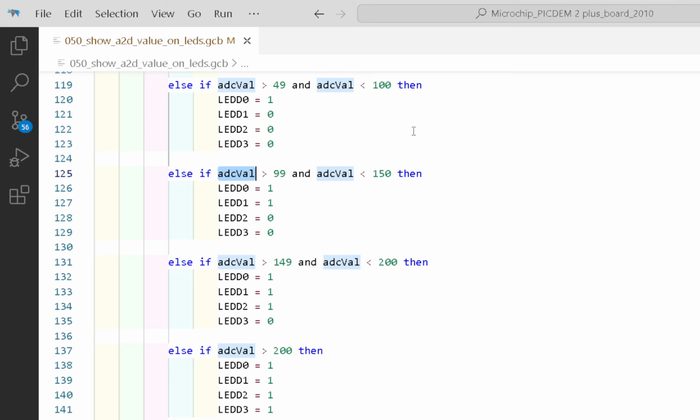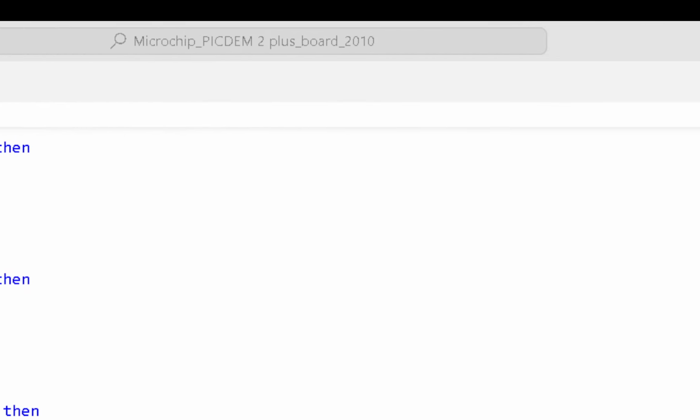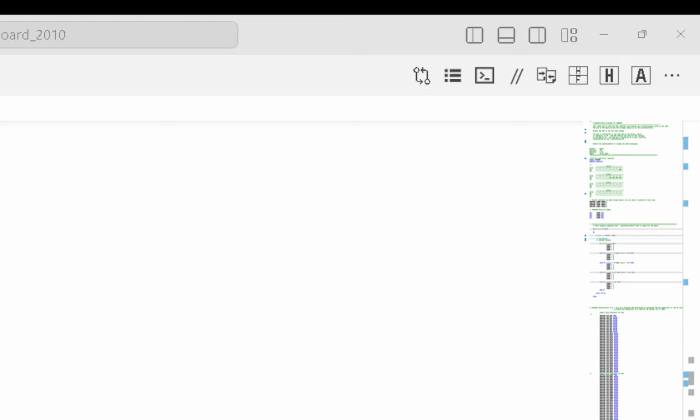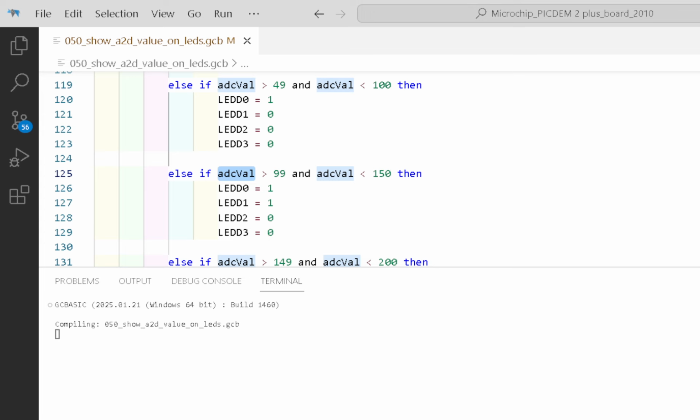Let's program that. What we're going to do is have a quick look at another way of activating programming. I'll just pull in the editor. Look, top right-hand corner of the editor, there's a set of icons. A means make assembly. H makes the hexadecimal file. H and F make the hex and flash. Let's do that. I've just pushed it. Did I push it? Oh, there you go. Oh, I'm so sorry.